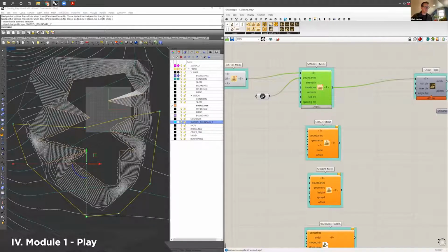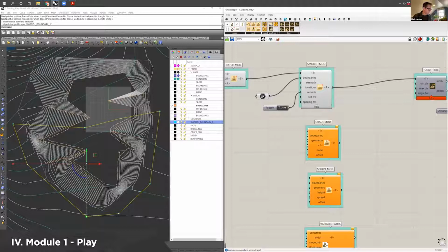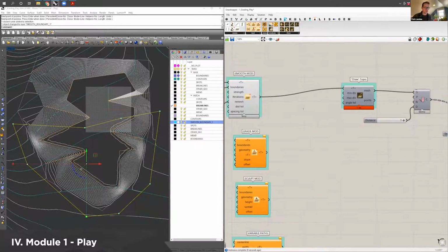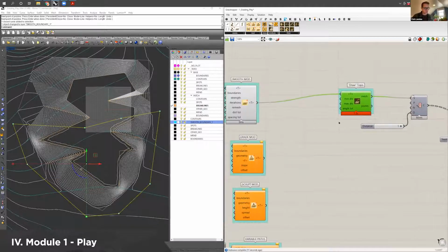Another one is to do a remesh, and remesh is kind of crazy, but remesh is actually using the new Rhino SubD modeling. And if I did that, it just needs a toggle. So I just say TOGG, toggle, a Boolean toggle. And then you plug that in to remesh and you double click. And suddenly you'll see that the points defining the smooth are a little different. They look a little smoother, and you have fewer points.